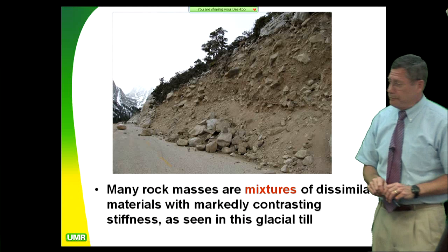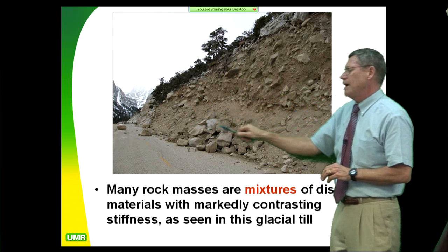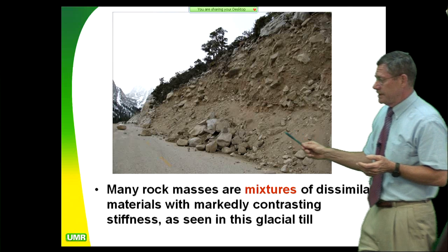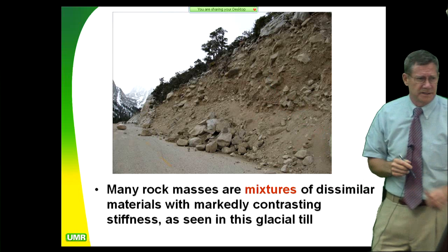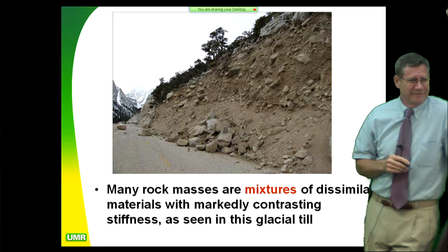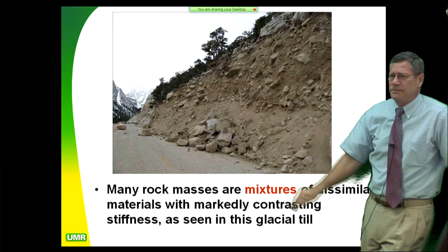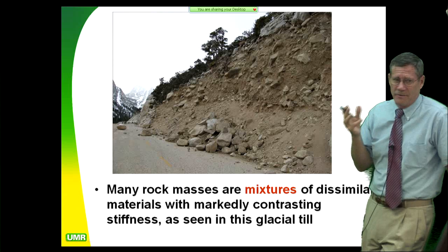The most problematic stuff I deal with, though, is glacial tills. This is what you have all over the Hindu Kush. You have glacial tills. Glacial tills are like trying to get C and phi values on landfills. It's impossible. Why? Because it's a heterogeneous assemblage. That's a big college word for a whole bunch of crap of all different kinds of sizes and roughness.